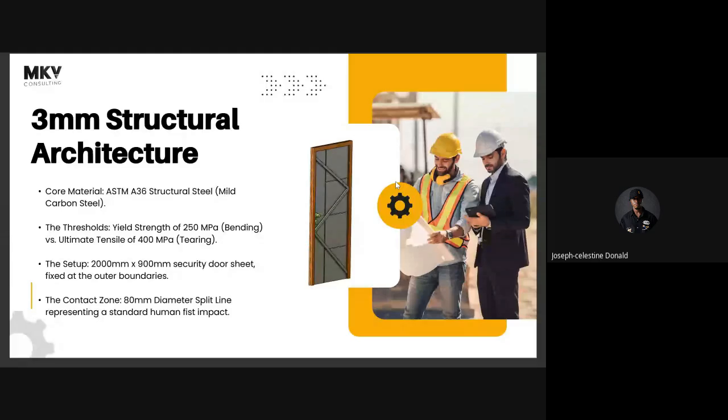Now, like I said yesterday, what are the first things you do when you start a simulation? If you remember, I said geometry, material, fixtures, your force, your mesh, and then your result. Now, material, we're using mild steel, the ASTM A36. The only value of importance there is the 36 at the end, which tells you its strength grade. And the ASTM at the front tells you under which standards the material falls, which international standard or certification standard you are working with.